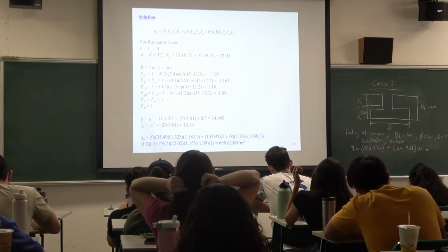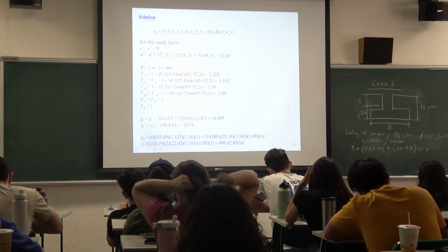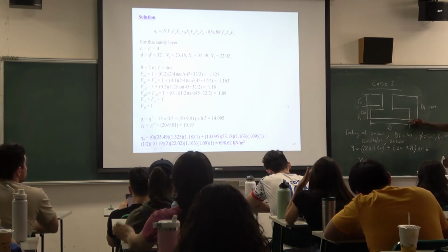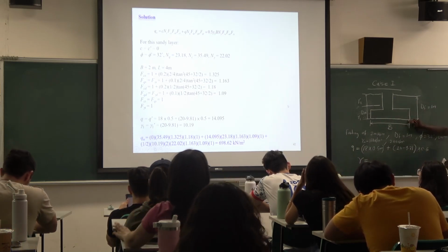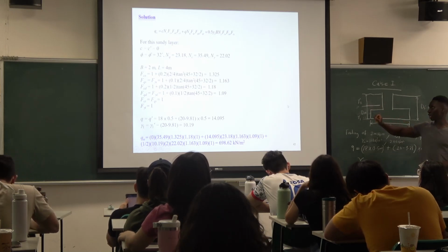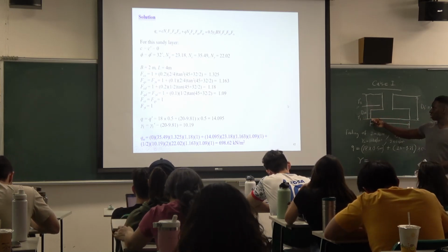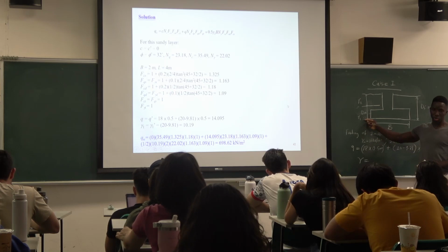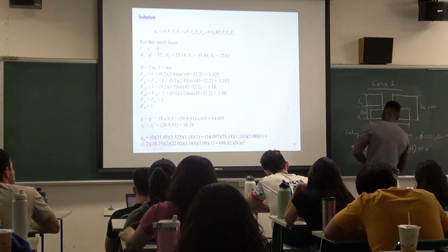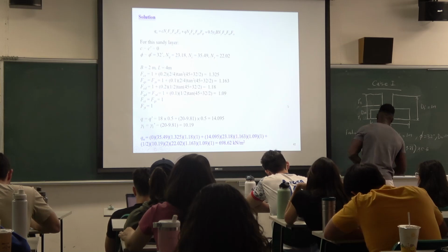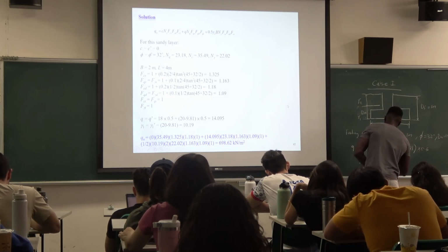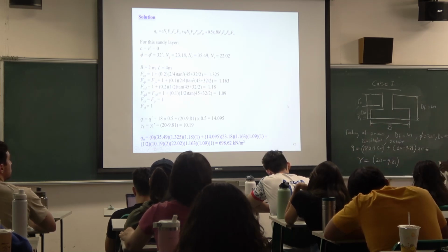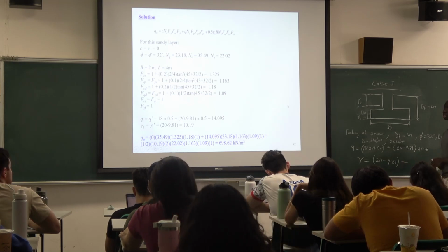And then for the gamma, you are going to use the gamma side. So it's the gamma at the base of the foundation. We have two gammas. We have 18 and then we have 20. But this foundation is on the soil layer in which the gamma is 20. So we have to use that one. Okay, so we say gamma will be 20 minus 9.81. Okay, and then you also get that value for your gamma.